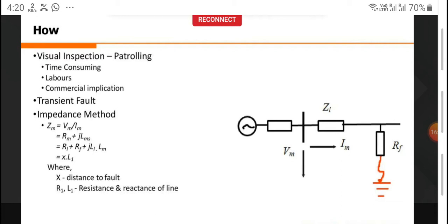by I. Whenever the impedance in that particular zone of ours is less than the target value, or less than the triggering value, that particular system gets triggered. That is our fundamental concept, because it signifies that whenever there is a fault, your current will go up and your voltage will drop down. So this is how your impedance method works.